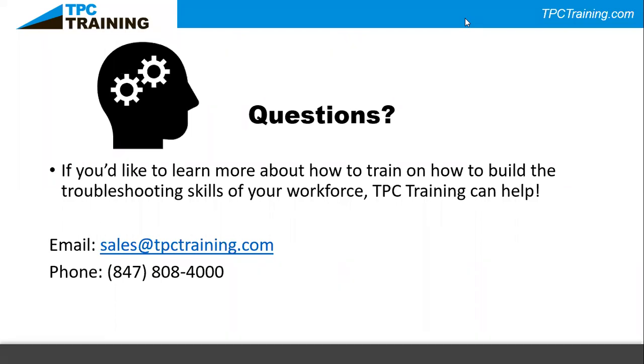So thank you for those great questions. When should I wear gloves to protect myself against electrical shock and injury? That's a really good question. Thank you for that, in terms of the PPE and protection. So, electrical arc rated and voltage rated protective gloves have to be worn anytime you are facing the risk of an electrical shock, right? According to NFPA 70E.